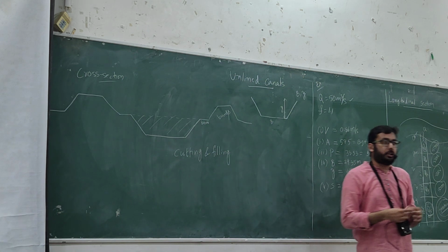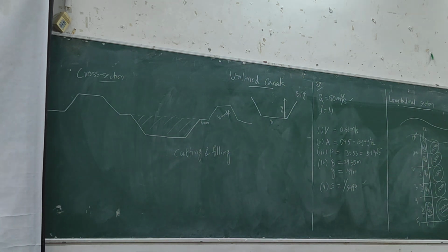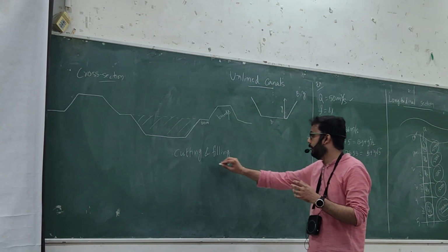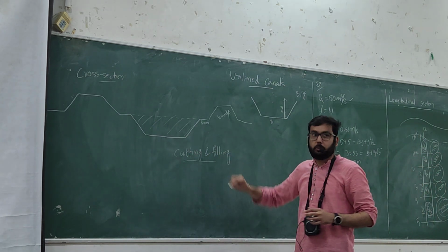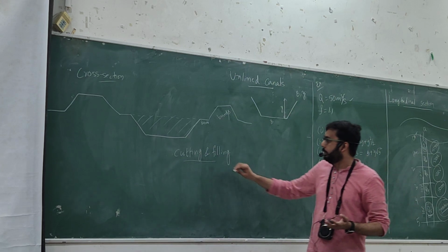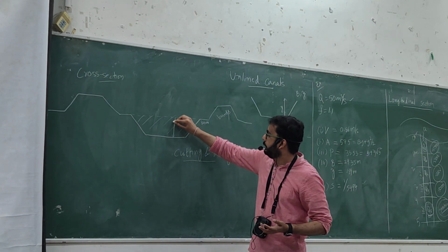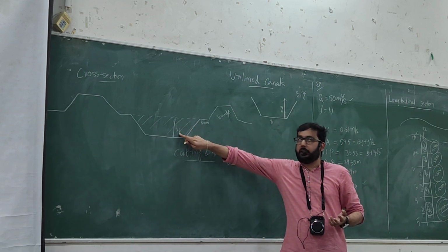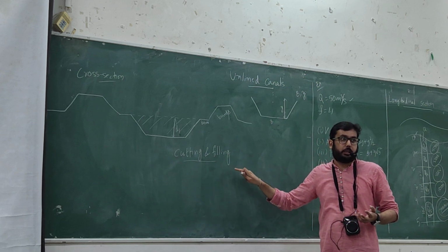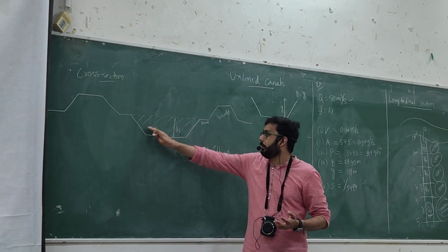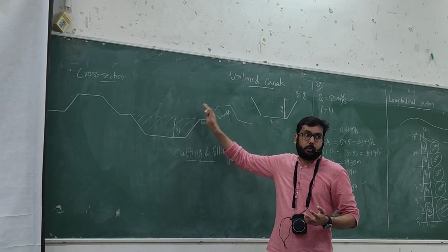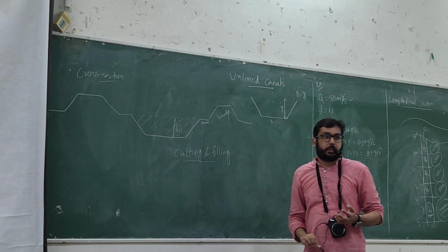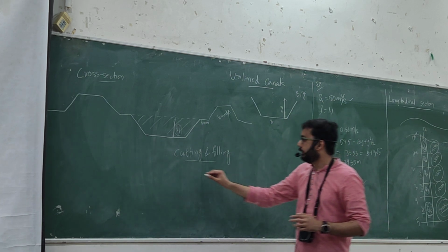Now, what would be the most economical scenario in cutting and filling? Yes, so whatever we cut, if we are using that for filling, then that would be the most economical scenario. And this can happen, let's say the canal depth is D1 or D, then there would be only one depth for which cutting and filling are equal. So whatever amount you are cutting from this section, if it is entirely used for the banks, then there could be only one possible depth, D1, where cutting and filling are equal. So this depth D1 is called the balancing depth.